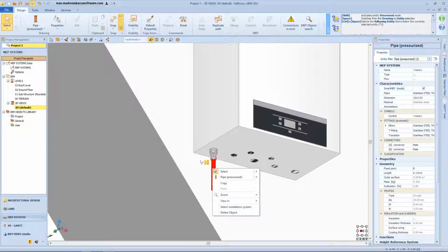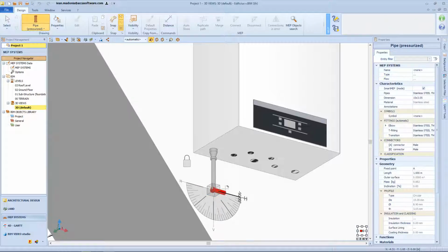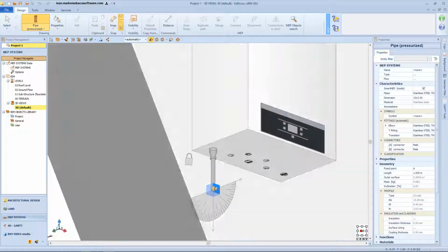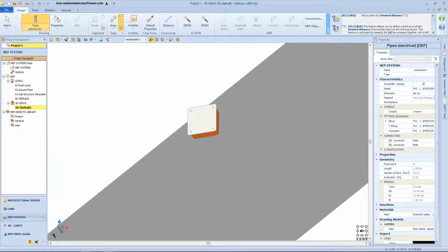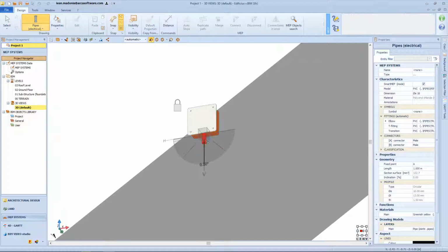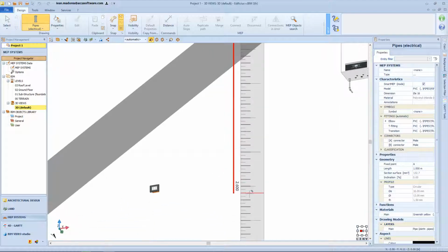Once a first connection section has been made, it's possible to use the directional cube and protractor to proceed in a different direction, obtaining the insertion of the necessary automatic fittings. By clicking on the yellow area of a surface connector, the directional cube and the protractor are enabled. These two tools are completely similar as to other functions and uses seen so far for the tracing connections in 3D.